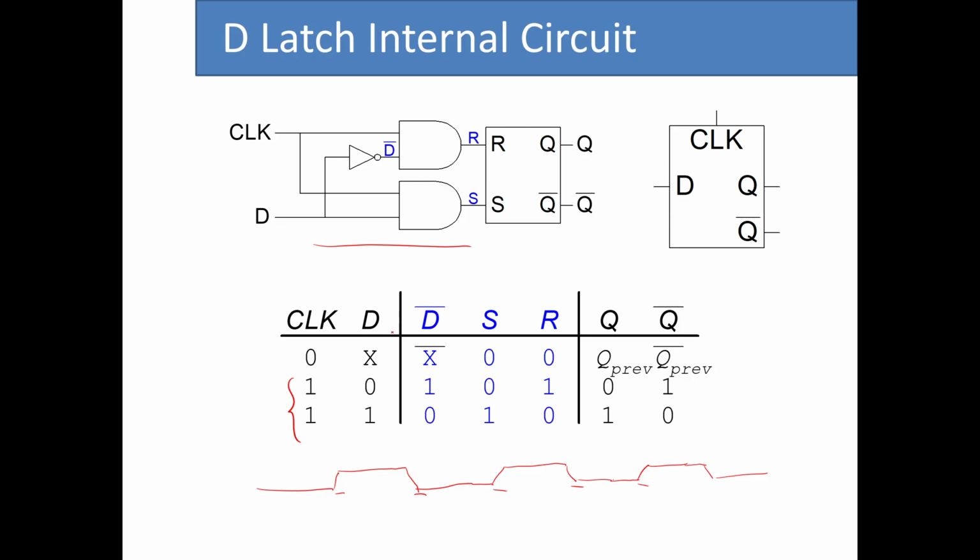So in the design of the D-Latch, whenever we are in this region, for which clock is 1, whatever change that we have in D is reflected at the output. So assuming that we have a clock signal that looks like this, which 50% of the time is 1, 50% of the time is 0, that means that half the time whatever change we make in the value for D is going to be reflected at the output.